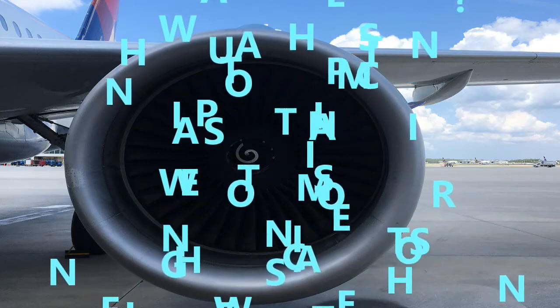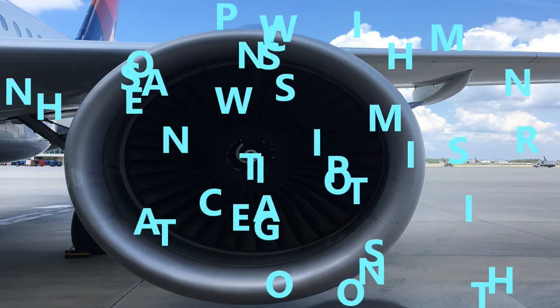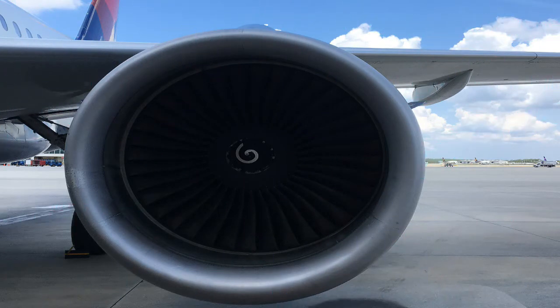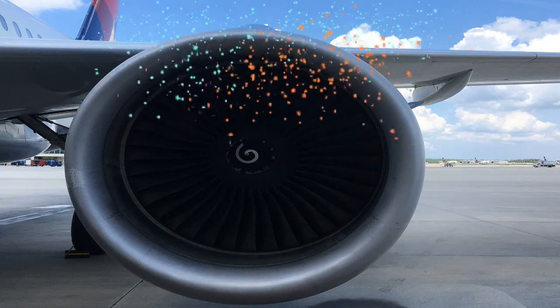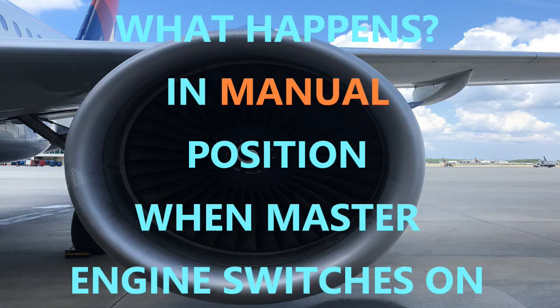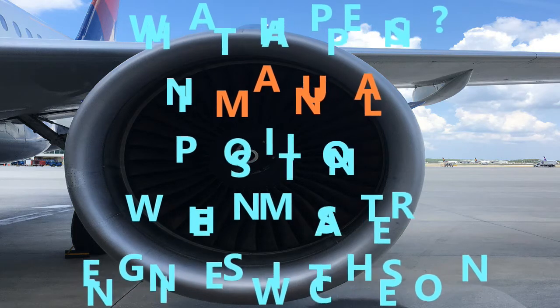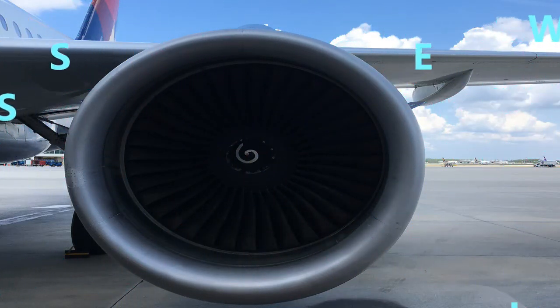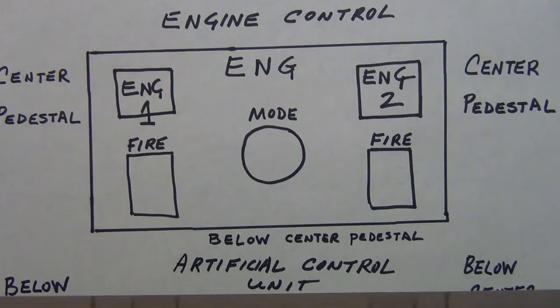You have your low pressure and high pressure fuel shutoff valves. When you're in automatic, the only valve that opens as far as your fuel goes is your low pressure one. If you're in manual start, that's different. In manual start, both the low pressure and the high pressure shutoff valves are opened. Okay, so you see what the comparison is between those two modes. You know now what that is. So again, make sure you make a note of that.